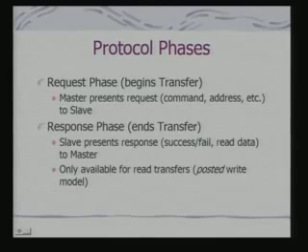The response phase ends the transfer, where the slave presents a response, success or fail or read data. If it is a read operation, data has to be presented to the master, and this response phase is typically available for read transfers. Something similar was there in ARM too, but here we are trying to evolve generic protocol phases and protocol definitions.